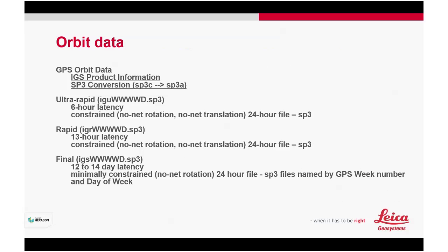And there is some of the data, the orbit data. Let's say you are carrying out very precise or high accuracy measurement, and your customer needs to wait for the so-called precise ephemerides. They have to wait about 2 weeks, and then you can download from the website and get the precise ephemerides.